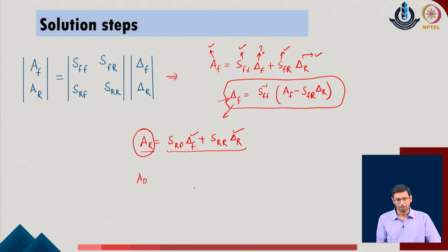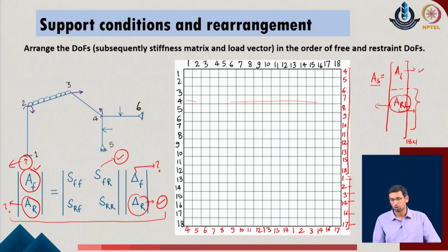That is why we say that the final value, or the ultimate value of the reactions at the system, will be A of R, which has been already evaluated over here, plus the minus of A of RL. So, A of RL is the contribution with respect to all these degrees of freedom which are restrained in the given problem. These are the contribution due to the external load.